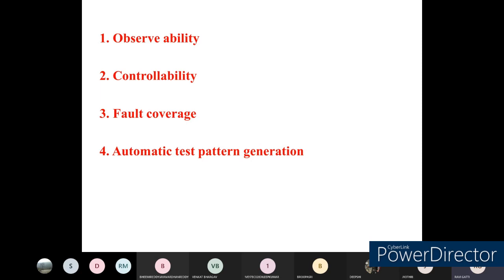Next, if the circuit is not artificially set to 0, or if any discrepancy is detected between the fault machine and the functional machine, then the fault is marked as detected and the simulation is stopped.